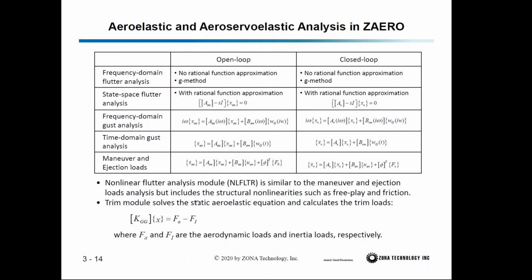And the last module is called the trim module. A trim module solves the static aeroelastic equation and calculates the trim load. So F sub A is the aerodynamic forces, F sub I is inertial forces. So the net force at a trim condition is applied to the structure, then we can calculate the structure deformation due to trim load.